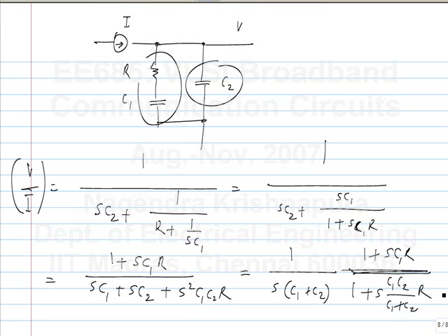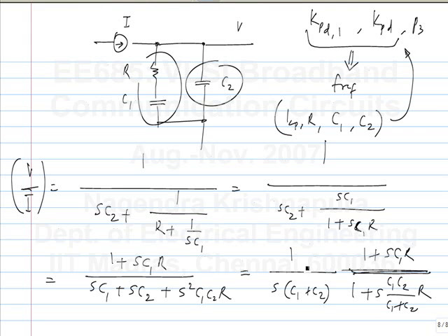So from this you can also figure out all the constants and pick the values of R, C1 and C2 correctly. So you have KPDI and KPD, and you know how to relate these two. Given some FREF, you know how to get these things. Now there aren't enough constraints without also a constraint on settling time, but that's okay. Let's say we'll keep the unity gain frequency as small as possible. That will give you a slow settling, but we don't care for now. Now we also know ICP, R, C1, C2, so actually you also know P3. So you design a loop, let's say in MATLAB, and obtain the values of KPDI, KPD and P3. Then you can choose the component values properly.